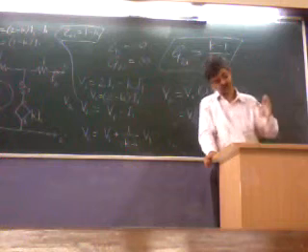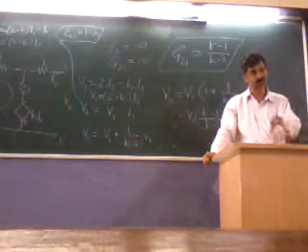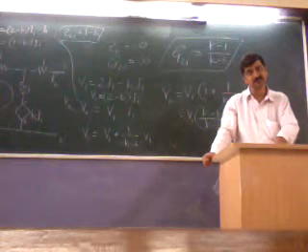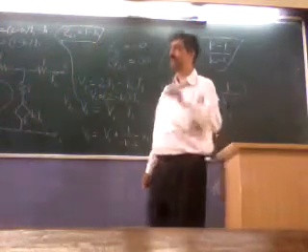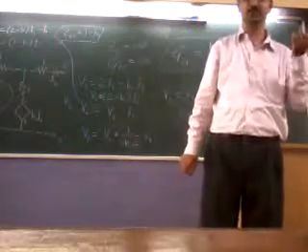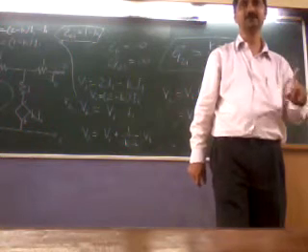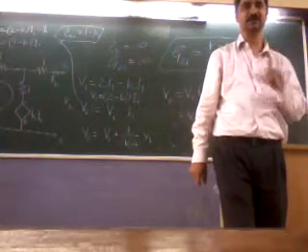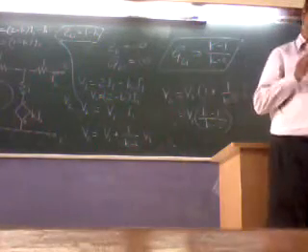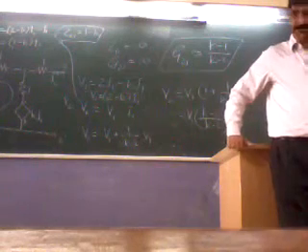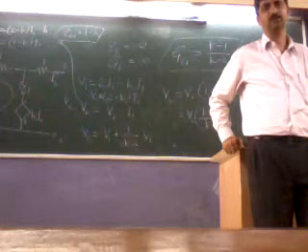Means a non-infinite or finite V1 leads to infinite V2. Bounded input is leading to unbounded output, and that corresponds to an unstable network. The network is not stable. So the concept is, if K is equal to 2, we are getting unbounded output, right?